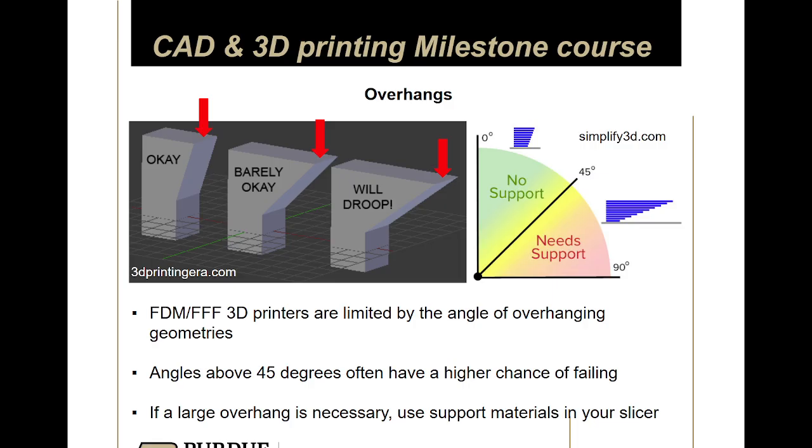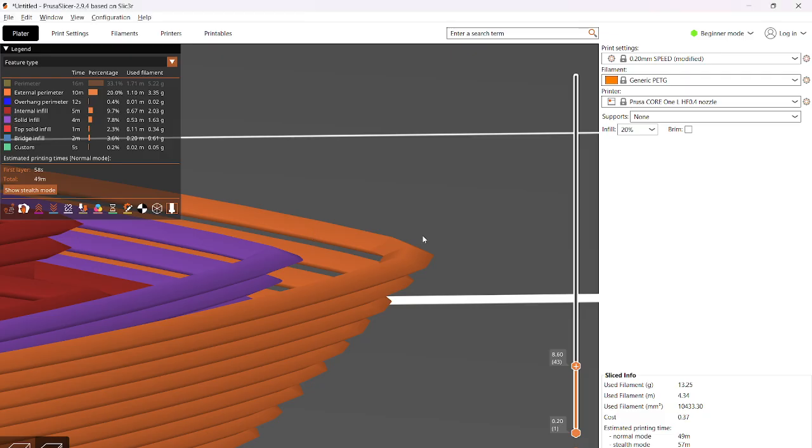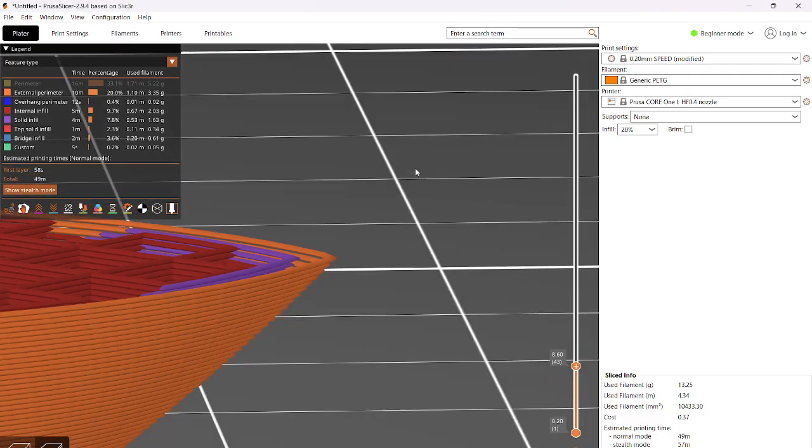So yeah. Overhangs can be found in not only these sloped surfaces, but you can also find them on holes. If you think about a hole, the top of the hole is an overhang, right? If you draw a line tangent to the top of a circle, it's horizontal, right? And it progressively gets more and more vertical as you go down the circle. But at the top, it's quite an aggressive overhang.